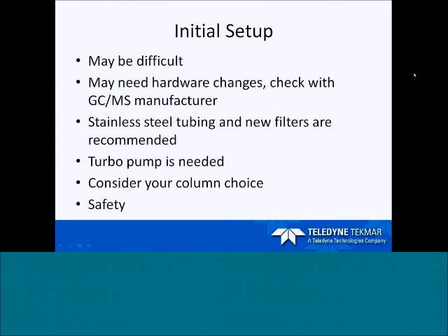We also recommend that you use new stainless steel tubing and new filters. And this is because hydrogen is a reactive gas, so if there's any residual impurities from using helium in your gas line, it will have the ability to react with them and kind of clean out the system.